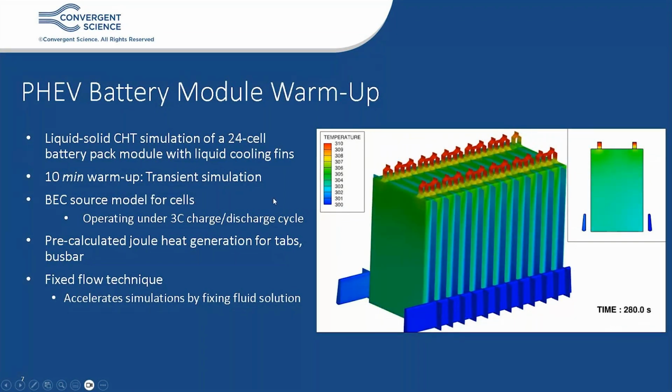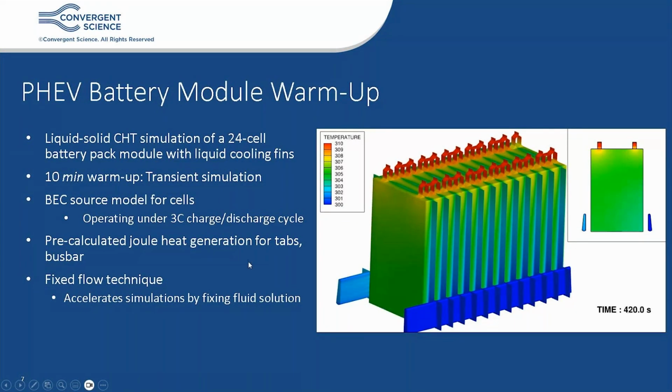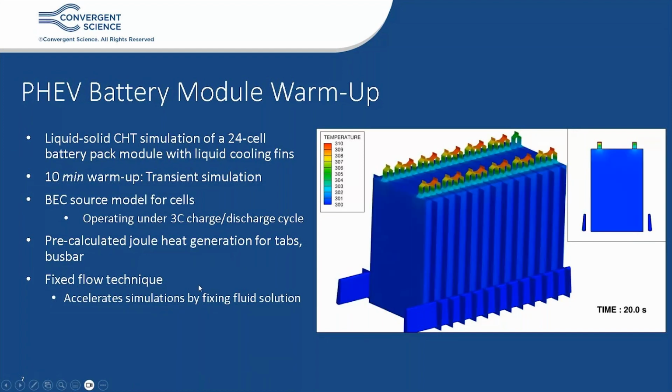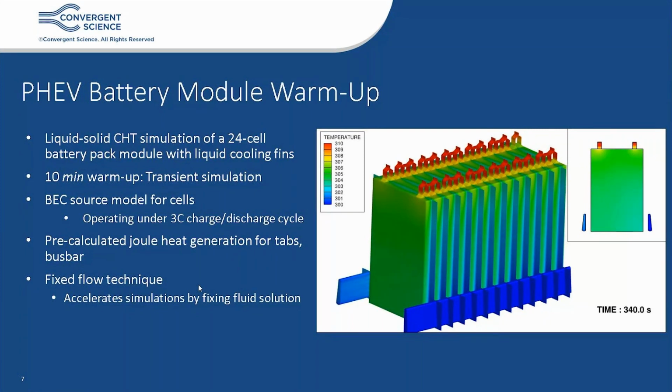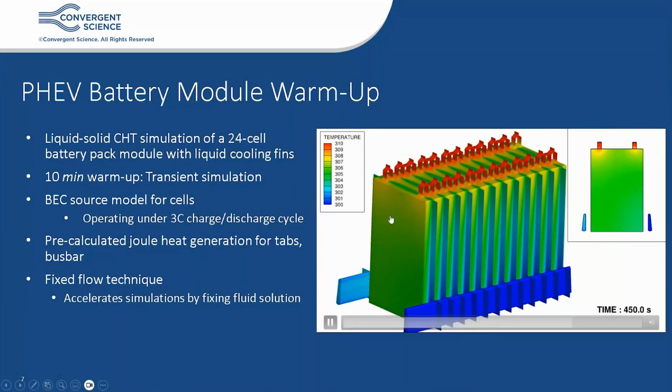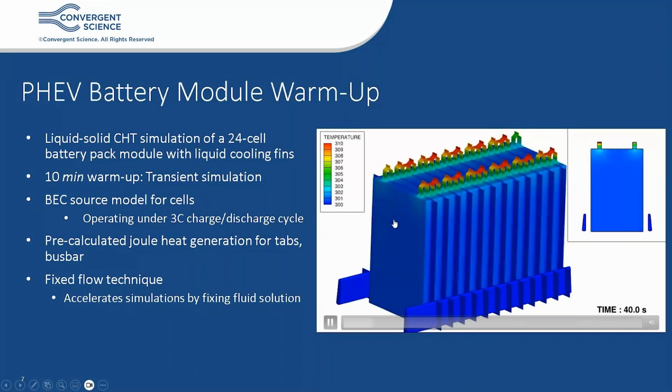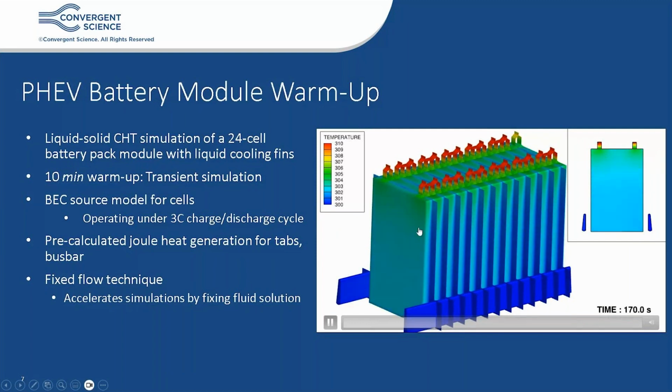Since these simulations are required to be run for long physical durations, we employ acceleration techniques like the fixed flow technique to speed up these simulations. And as such, you can evaluate a 3D temperature distribution inside the battery and the effectiveness of your particular cooling design.